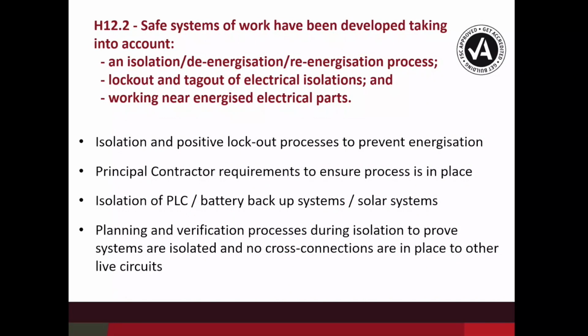We wanted to highlight one of the things that we are seeing more and more of in the current era of generation of electricity, where programmable logic controllers, building management systems, battery backup systems such as UPS and the like, generators, etc., and solar systems can provide a feedback loop when something is isolated and switched off. So we've had a number of incidences where people have turned it off, we've confirmed, but after a set period, the other system kicks in and we end up with a voltage that gets generated back into the system, which then becomes a potential danger.